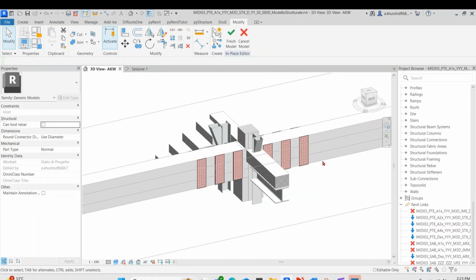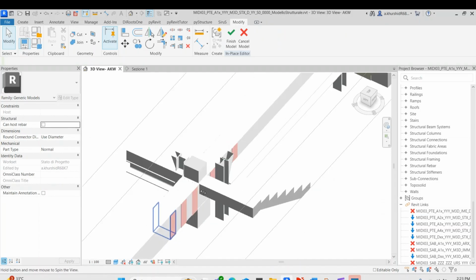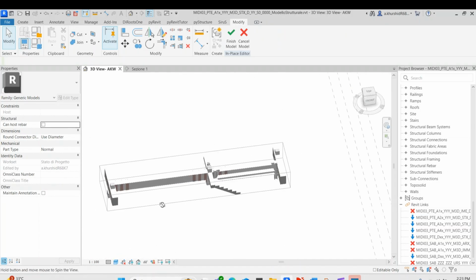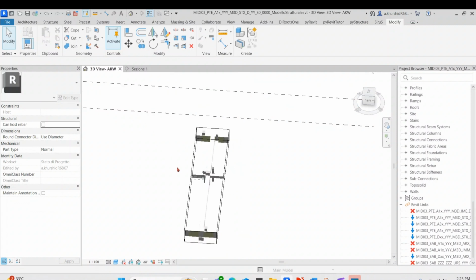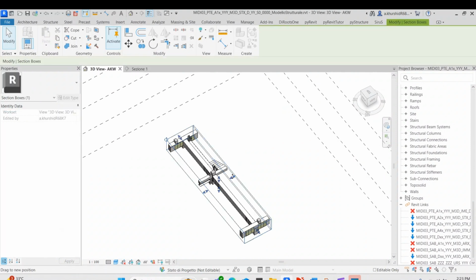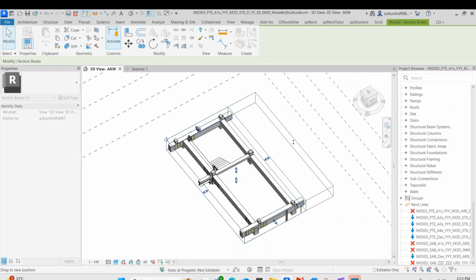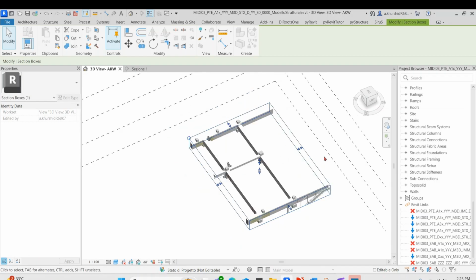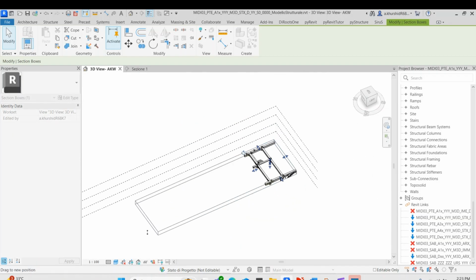Always make sure while modeling that no elements interfere with each other. The best industry practice is first avoid the clashes, and if that cannot be achieved, then we must try to reduce them. Anyways, we will need to correct the interferences in the later stages of the project.